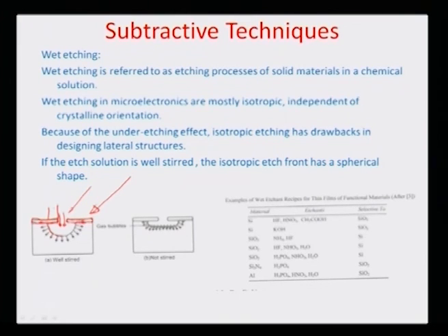Let us say this distance is x; this is known as the undercut, because it was not intended or planned, and because of the homogeneity, etching happens in the lateral as well as the vertical direction, which always results in this kind of an undercut. So, when you design microsystems and the masks for the microsystems, this undercut allowance has to be taken into account for the design.